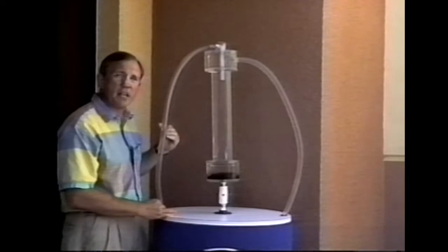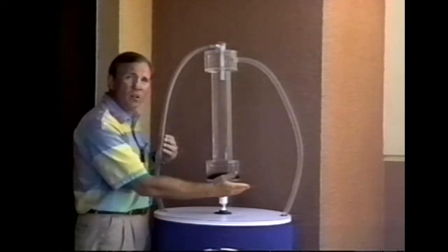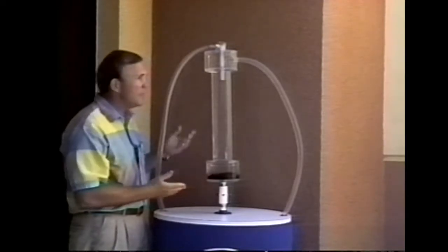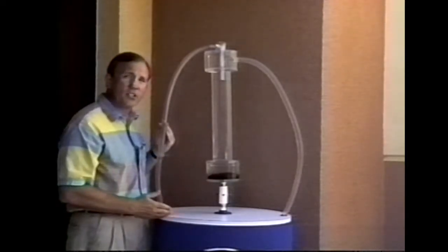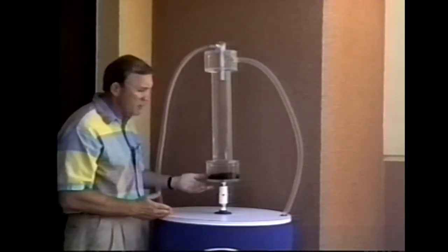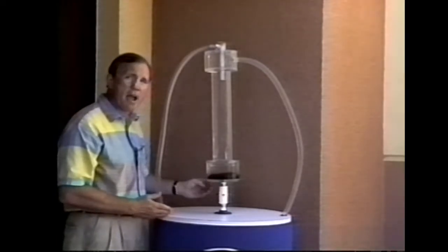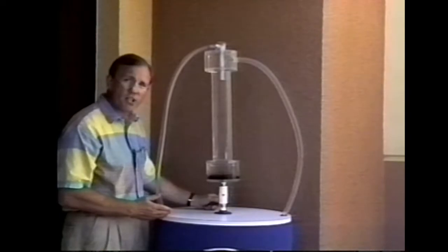out the top, and goes onto the system. So you're basically coming from your water well or from your water source, removing the sand and grit from that water, sending clean water onto the irrigation system. Material collected down in this chamber can be flushed either manually or automatically with a simple actuation of a valve.